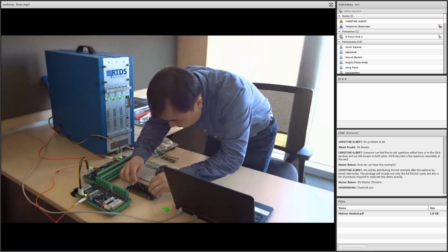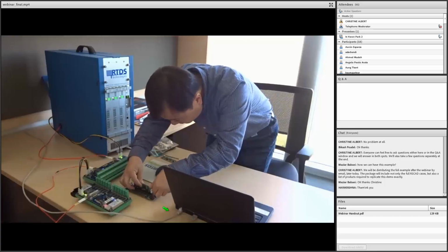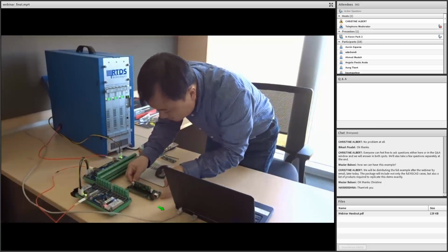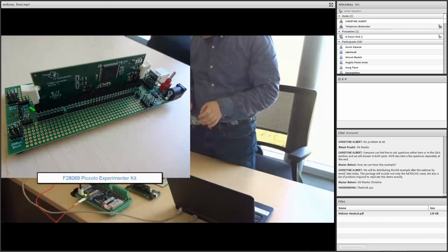It's very easy to put the card into the baseboard, and this is what it looks like when you put the card into the baseboard. We have 2 latches, so make sure that you put these latches into position once you place the card in the slot. And we have these pinouts at both sides of the card.